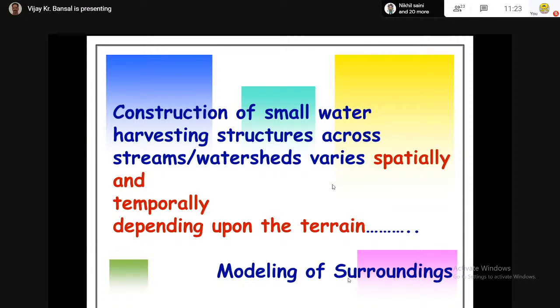Another very beautiful application is where BIM generates material requirements. You have a 3D model of a building. During construction, you can generate how much material is required. Even in the operation and maintenance stage, you can generate material requirements, depending on whether you are doing whitewashing or some repair work, and even during the demolition stage. So from the building model, material requirements during construction, operation and maintenance, and demolition may be generated.